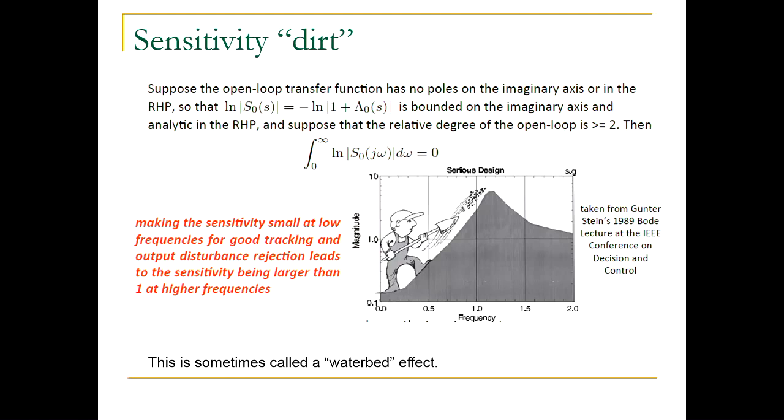So large open loop transfer function gain would result in small sensitivity transfer function gain, right? So if you are working hard to reduce the sensitivity gain in low frequencies, you will be piling that up somewhere above 0, where this area is positive, right? And this would hurt you. While you are making something desirable here, this is often very undesirable, right?